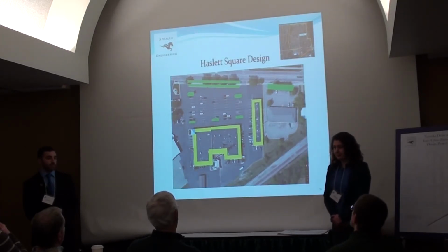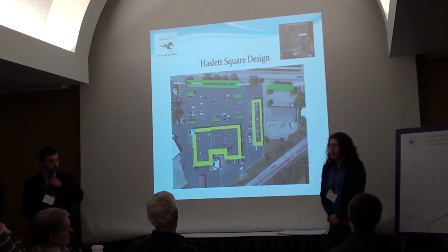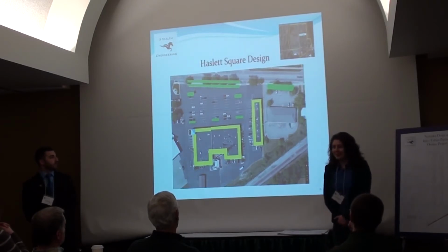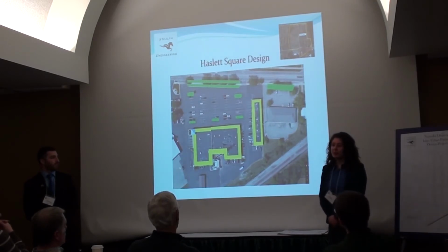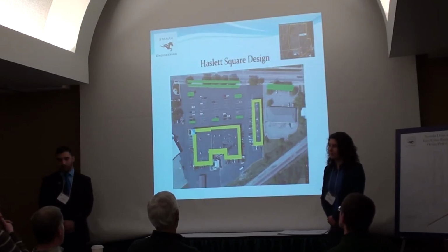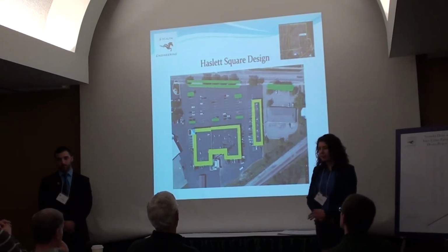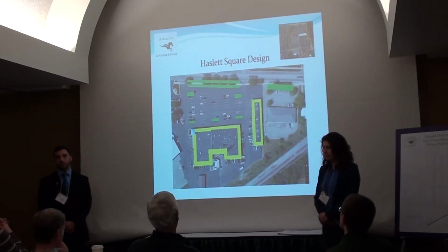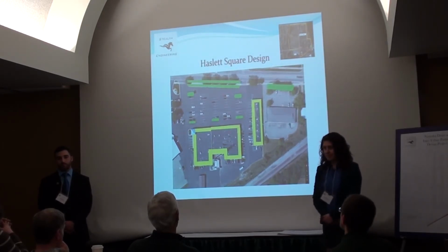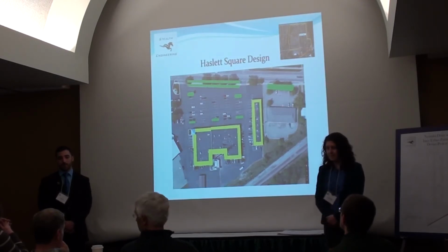And do you have soils information to tell you where the water's going to actually go? No. But we're probably going to have to bring in some new soil because the current conditions will not infiltrate very well. We would have about a 50% layer of sand, and compost and topsoil for the other 50%. Okay, very good. That's all my questions.